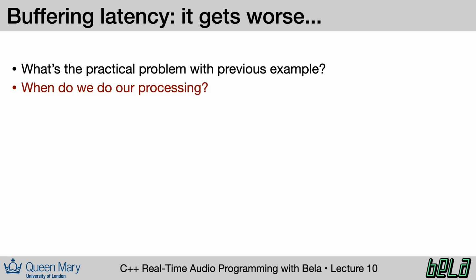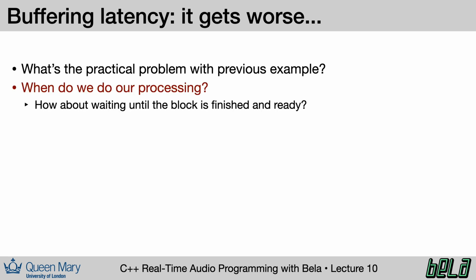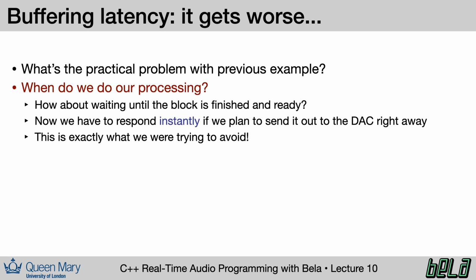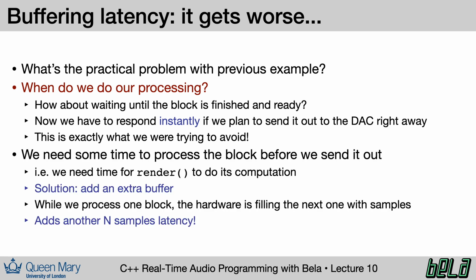Well, the question is, when are we supposed to do our processing? We might wait until the input block is totally finished and ready, but the problem there is that we have to react instantly if we plan to send that block back to the DAC right away. This is exactly what we are trying to avoid by having a block-based system. We need time for our computation to take place. Therefore, we're going to add an extra buffer of delay, specifically to give the processor time to do whatever our audio calculations are going to be.